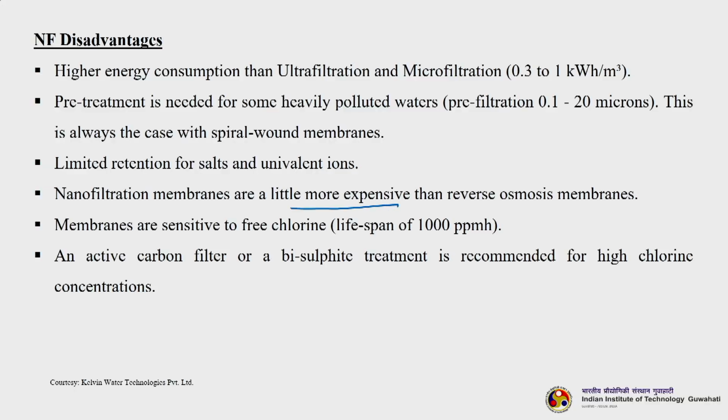So, limited retention for salts and univalent ions. Nanofiltration membranes are a little more expensive than reverse osmosis membranes. Membranes are sensitive to free chlorine. Most of the time chlorine is present in water and water streams, so they are not very good chlorine resistance membranes. Lifespan of around 1000 ppm-hours. Okay. So, an active carbon filter or a bisulfite treatment is recommended for high chlorine concentration.